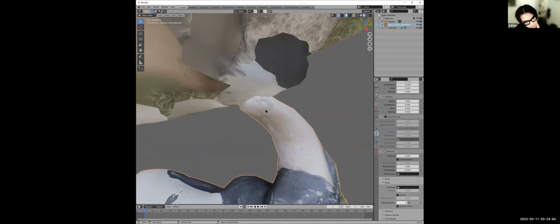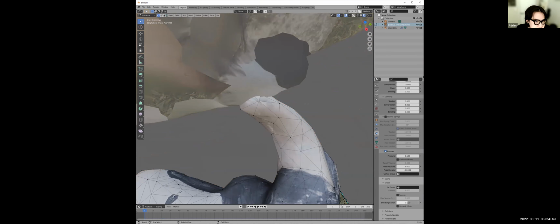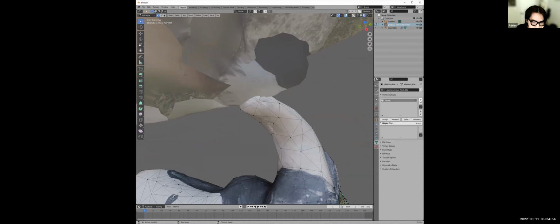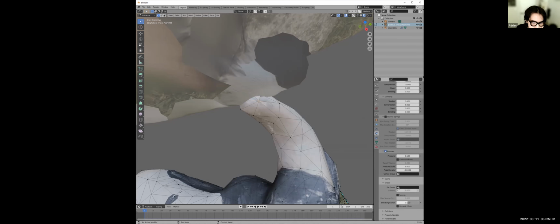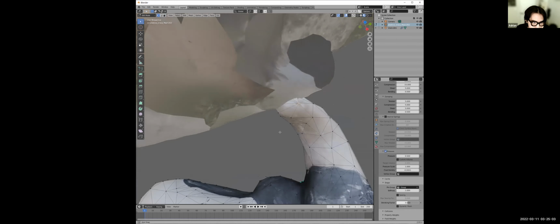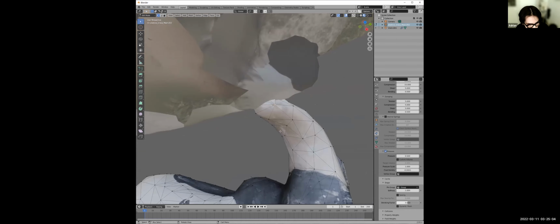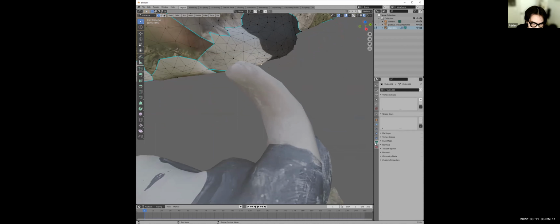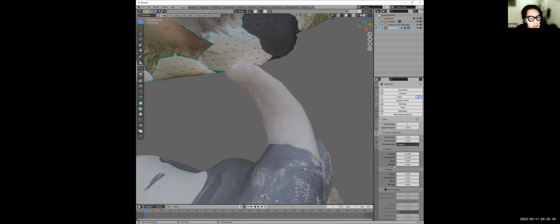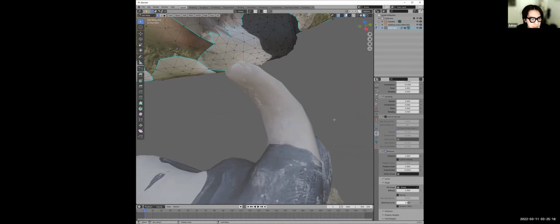So the first thing we'll do is hit Tab on the cow. We'll select a vertex, go into vertex select mode, select this vertex, go to the green triangles, make a vertex group, assign it to that group, go into the cloth properties, under shape, select that group for your pin group for the cow. Then the violin we'll do the same thing: select any point, maybe this point, go to vertex groups, make it a group, assign it, go to cloth, shape, set that pin group to this group.